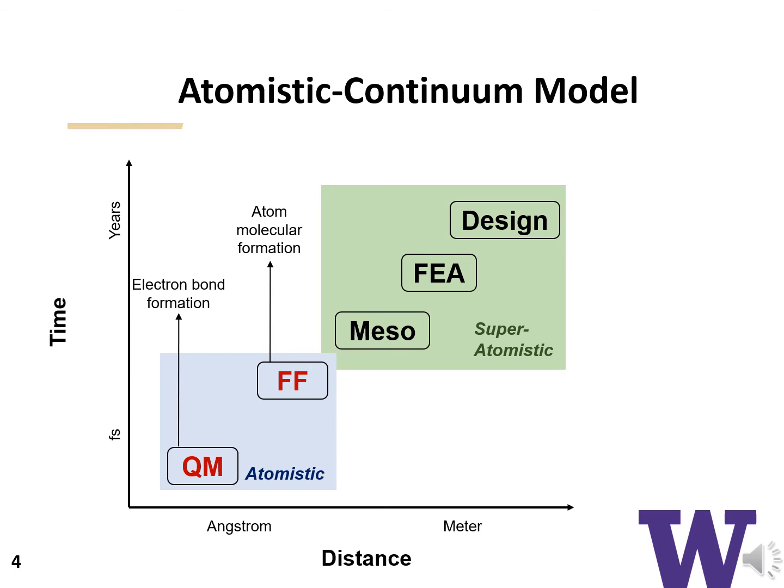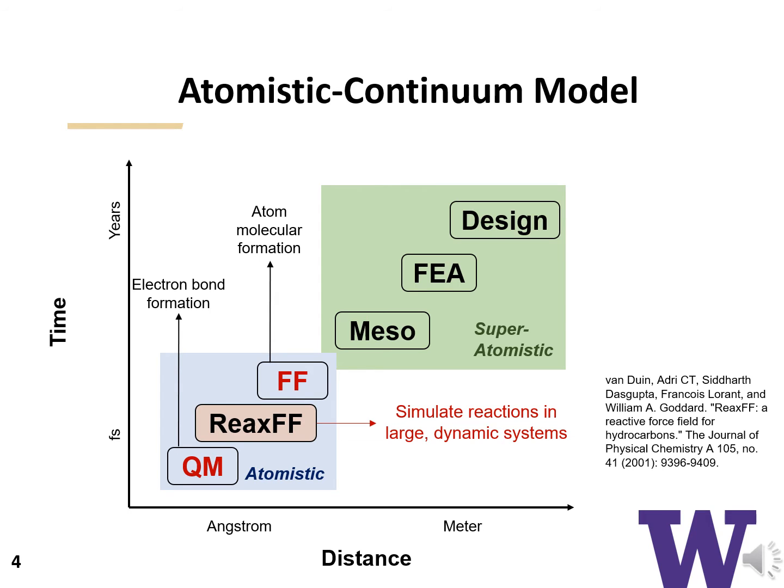I will start off by showing you the time-distance landscape for simulations. Atomistic simulations can be carried out using either quantum mechanics simulations, where only few atoms can be simulated, or force field methods that can simulate larger systems but are not as detailed as quantum mechanics calculations. ReaxFF bridges the gap between quantum mechanics and force field methods, as ReaxFF can simulate dynamic events for large systems.